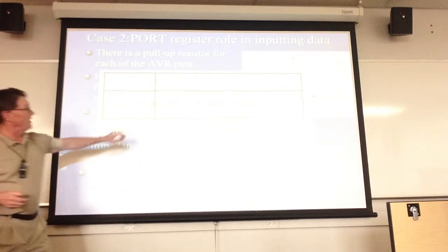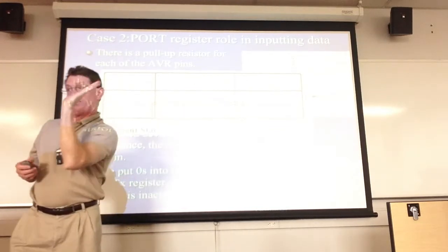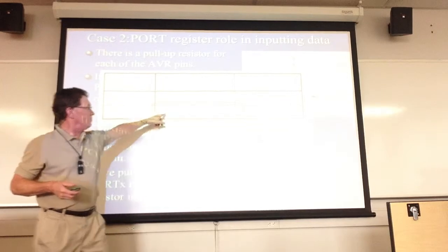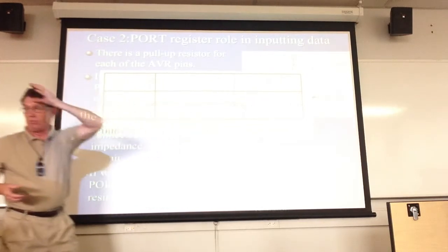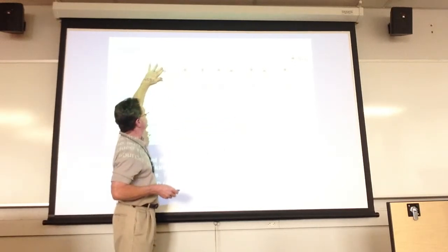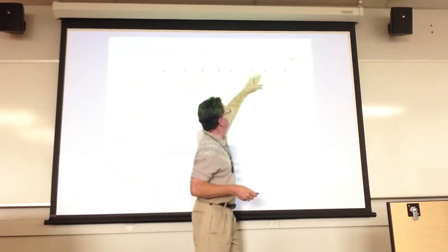all right? So in effect, if PORT X is a 0 and DDRX is a 0, that switch is open circuited on the pull-up resistors. Okay, they're not activated. If I force that to be a 1, I'm using it as an input, and I'm activating my pull-up resistor there. Okay. So basically you have the PORT X register. If we set it up as all inputs, this switch is open, so that pull-up resistor is deactivated. This one is 0, that's deactivated, and this one is 0, that's deactivated. Those are generally going to be left in a high impedance state there.